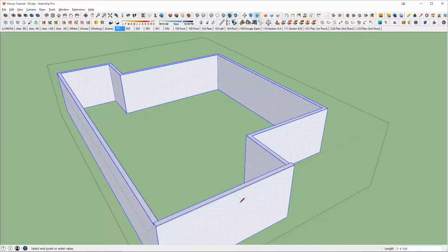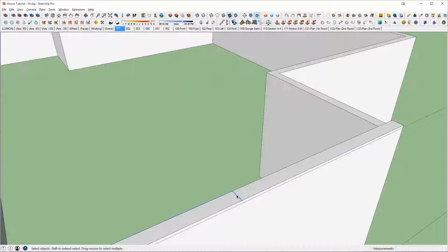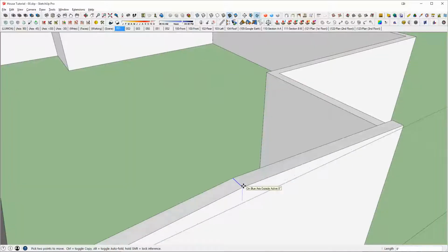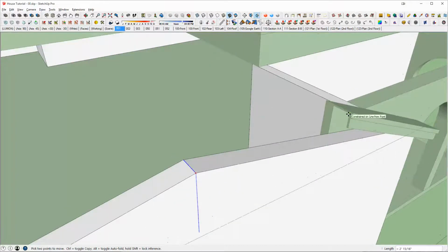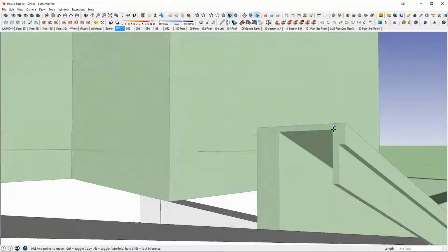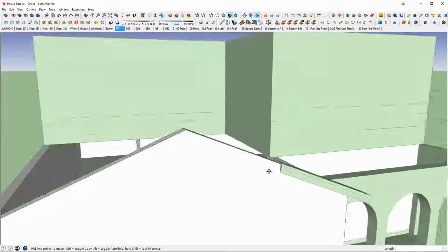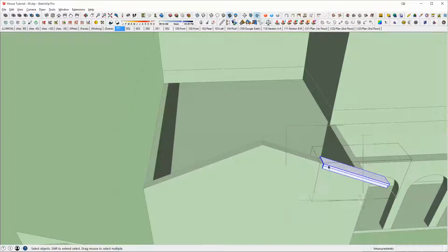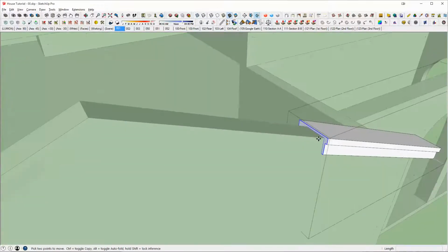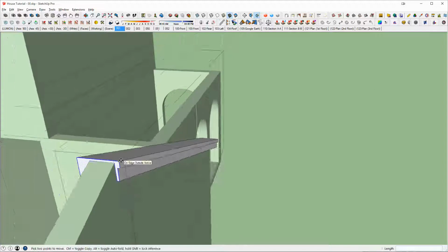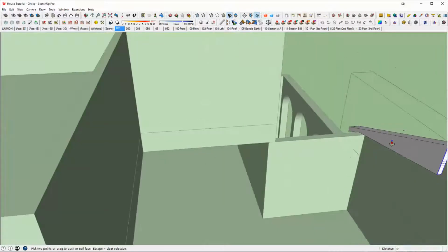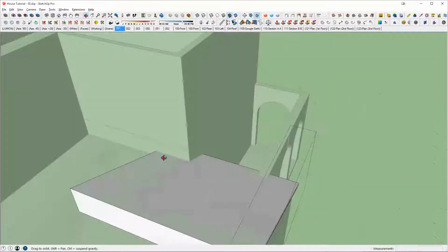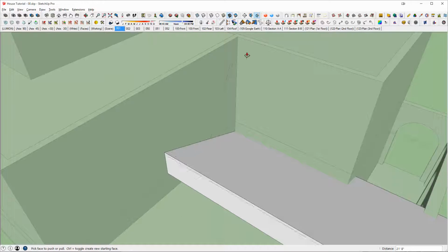Right in the middle, I'm going to split it, grab this line, and if I move this line in a vertical fashion and snap to this plane, you can see that I have my gable wall built, and now I can just simply grab this piece and stretch, come right up there, and then I can push pull this all the way back to here.